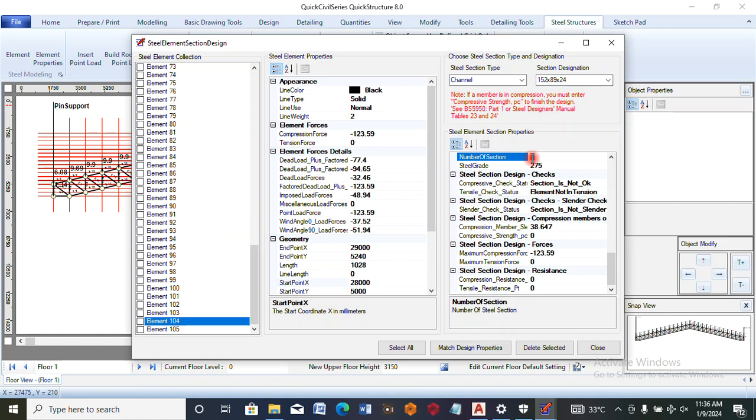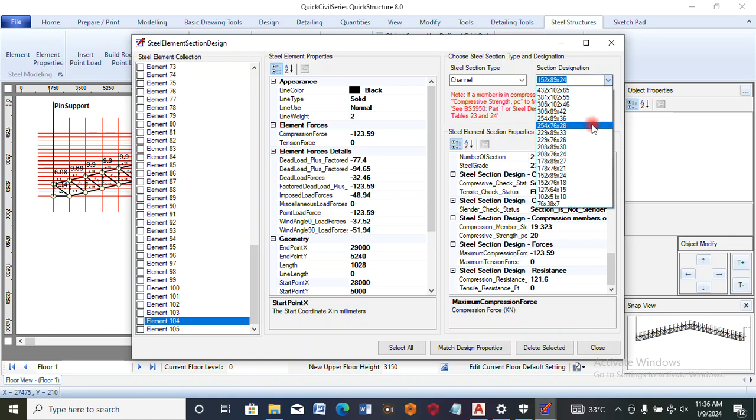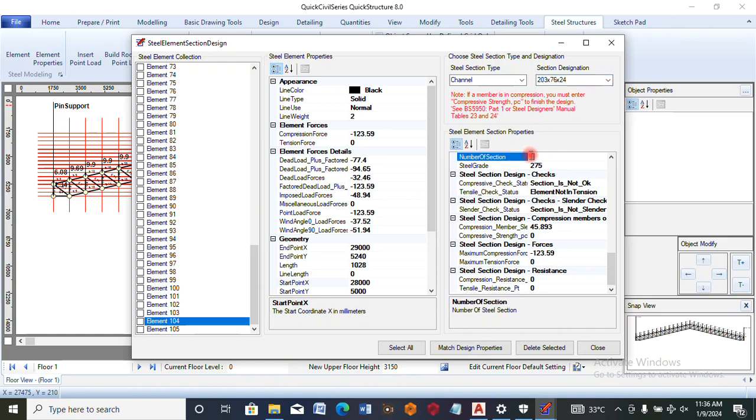Number of sections, 2. And try again. If it doesn't work, I will still move up. Section is not okay. And so steel design is all about trying different ways. Pick an element, you try, you pick until the one that is safe, and you try to be economical. I can actually pick the first one, but you discover that it may not be economical. So actually try from the list. You keep on progressing that way. So let me choose this section, C2.